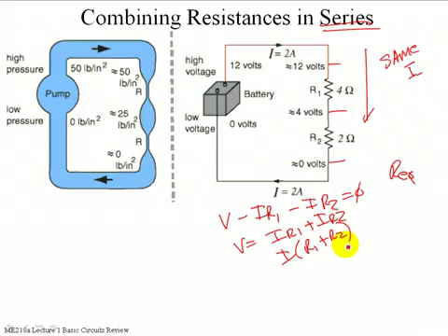So I'm sort of harping on this because it's a really common thing that I see. People assign a greater degree of accuracy to the physical components than they actually exhibit. And so you've calculated this thing on paper and you want to try and make it like what you calculated on paper, and that really ignores the reality of the tolerances on these physical devices.